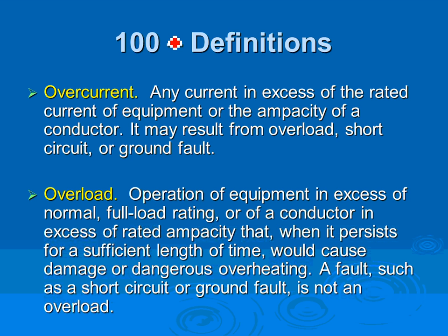A ground fault is phase to ground. An overload is a motor that's supposed to pump water to a 2-story building, and you install it to pump it to a 5-story building. So you're overloading it. A short circuit, you grab phase A and phase B, tie it together with a wire nut, and you flip the switch on.